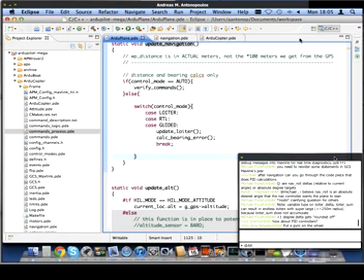Okay, so the way auto launch works is, first of all, you need to have a launch or takeoff command in your mission. If you have a takeoff command in the mission and then you enter auto, the plane will fire up the engine and increase the throttle, and it will try to keep the heading pointing along the current compass heading.